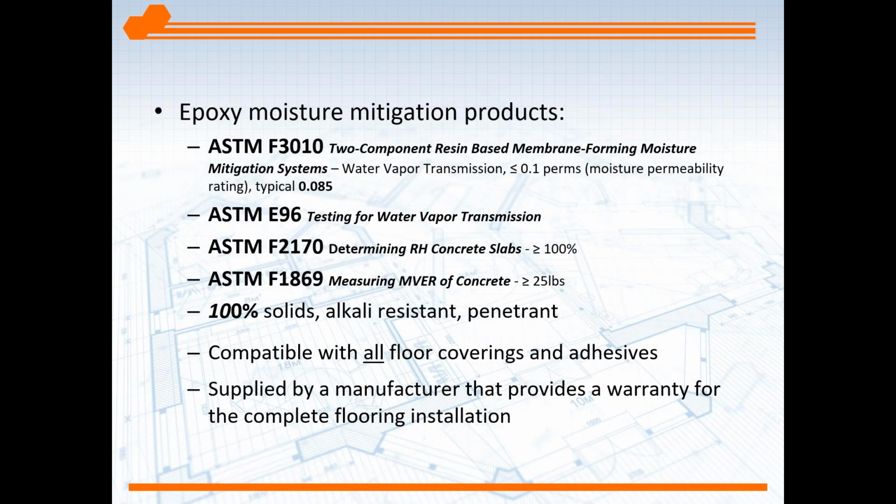Also important, 100% solids, alkali resistant, and their penetrance. And when I say penetrance, they're able by formulation to wet or wick into the concrete. If you recall earlier in the beginning of the slide presentation, I showed you an epoxy that was blistering up. Oftentimes, an epoxy will just sit on the surface. It does not penetrate well for a greater or better mechanical lock. So again, these epoxy moisture mitigation systems don't just sit on the surface, they wet in, becoming much more effective for the process or reasons of moisture mitigation.